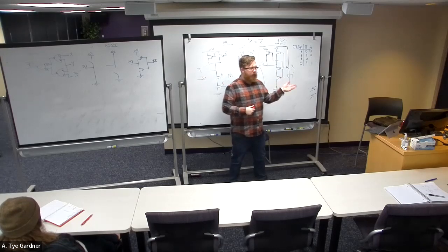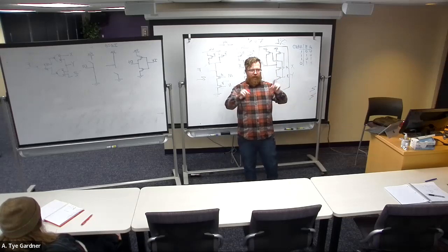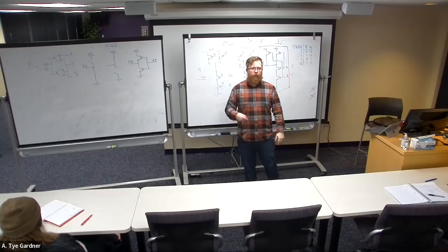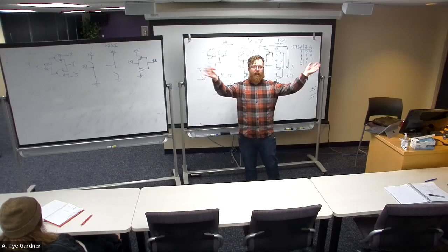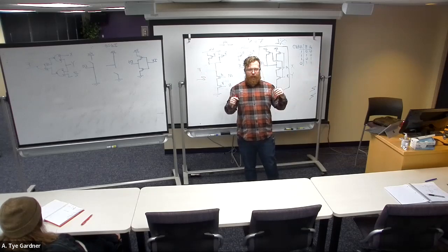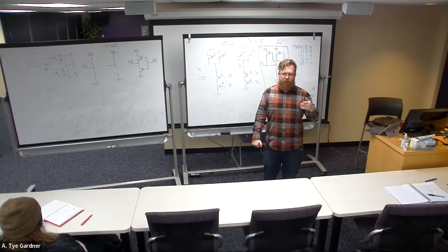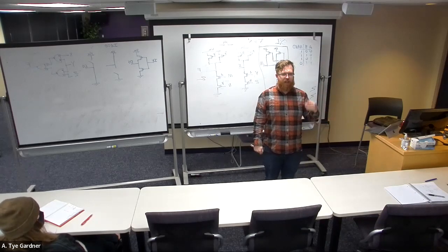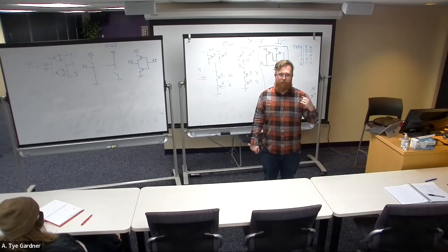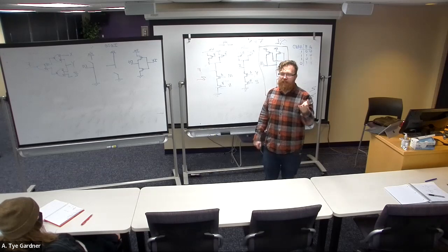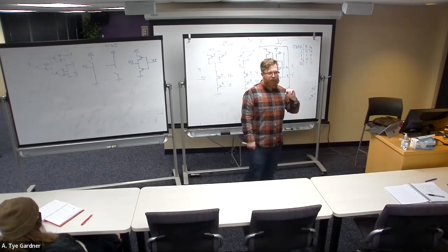We have things called microcontrollers, which you can program, and they interact with the outside world by putting ones and zeros on their pins. But if it wants to control or talk to many other devices and it only has 16 pins, then I may want to consider how to limit the number of pins. So it's not uncommon to use two-wire communication, where two devices talk to each other back and forth, in both directions, using only two wires. It's easy if I use three wires. One of those wires has to be ground because I need a reference.